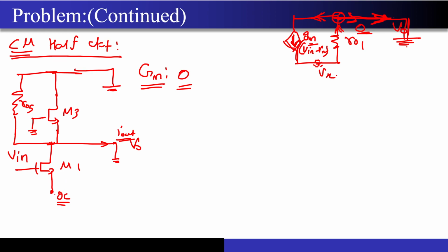So now this is what we are expecting. If the tail current source is ideal, the circuit should ideally completely reject the common mode excitations that I am giving at its input, correct? And this is the good news that we were able to see. I hope this is clear. If any doubts, please feel free to poke me, okay?